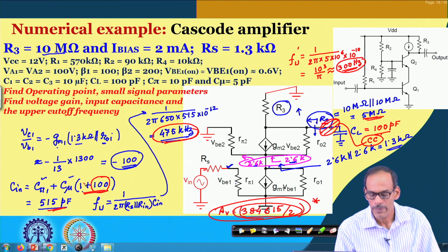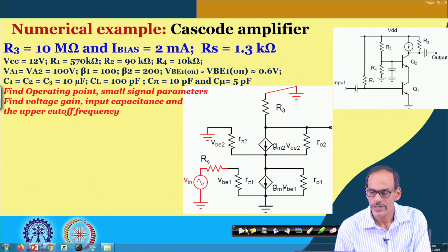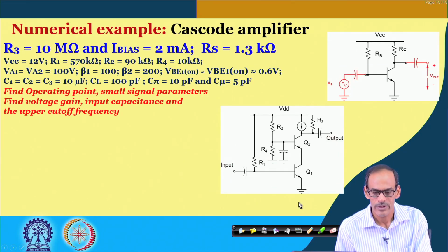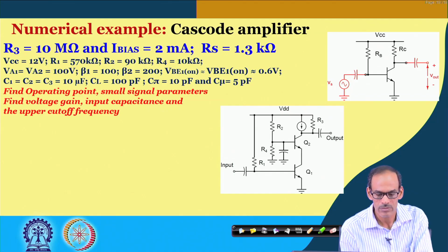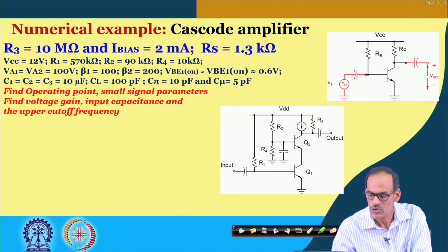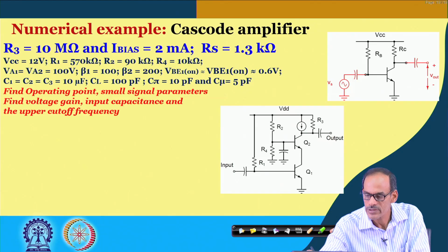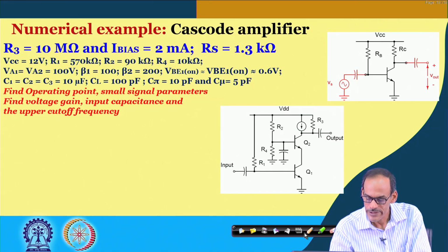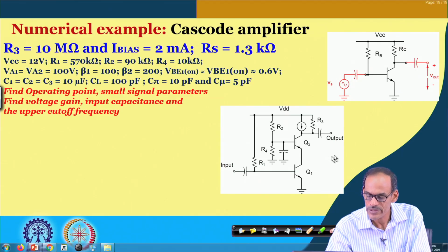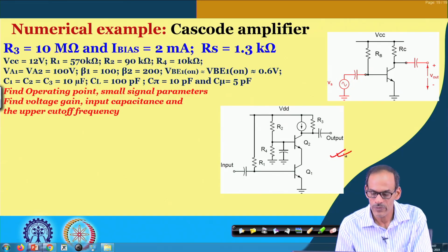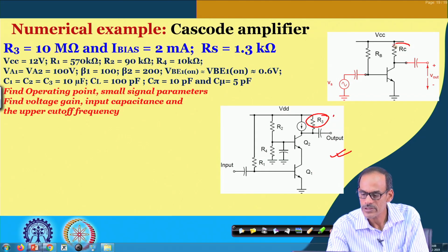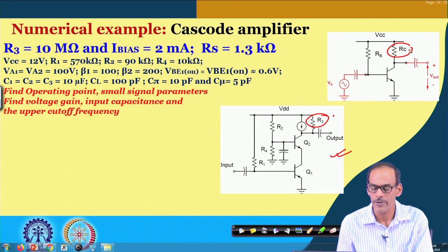Okay. So, so far we have been talking about the cascode amplifier using BJT. A similar kind of circuit can also be analyzed. In fact, this is what we were talking about. In case you are considering the CE amplifier and compare this circuit directly, it will be difficult to compare because this resistance is high, but then this resistance you cannot make so high.